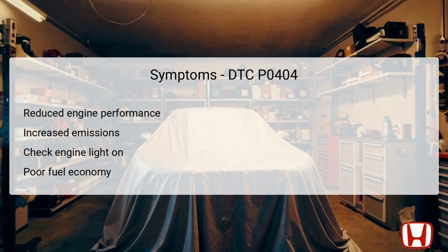The check engine light will illuminate as a warning signal to the driver, prompting further investigation into the vehicle's health. Additionally, drivers may find that fuel economy suffers, as a non-operational EGR valve can lead to suboptimal combustion conditions. Awareness of these symptoms is essential for prompt attention to the problem and minimizing further damage or more costly repairs.